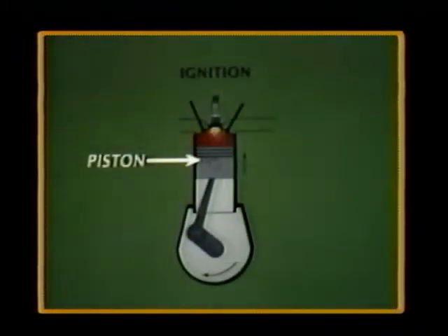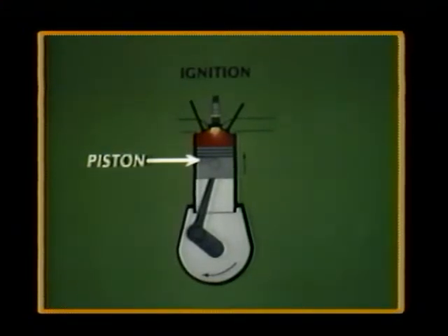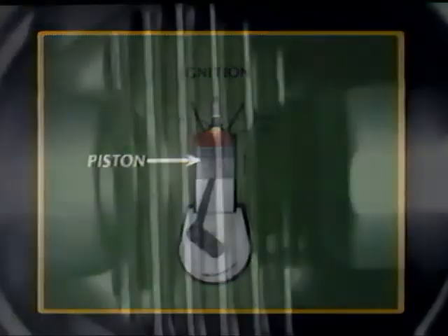The piston forms the movable wall of the combustion chamber. This component must be strong enough to withstand all of the forces from expanding gases and must form a tight seal inside the cylinder. The underside of the piston head is usually finned. This allows heat to transfer from the piston into the oil.